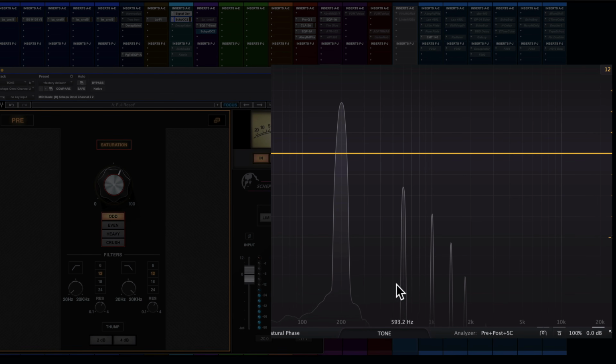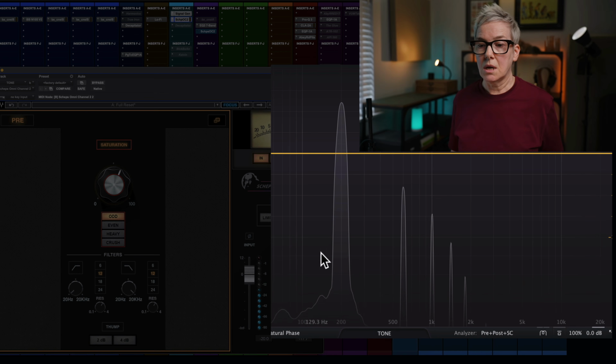So the original tone or note is 200 Hz, and odd harmonics represent the third, fifth and seventh harmonics and continue. We see that for 200 Hz we are getting a 600 Hz tone because 200 times third order, so 2 times 3 is 6, and then fifth, 2 times 5 is 10, so 1 kilohertz there, a harmonic, and then seventh on a 200 Hz tone, 2 times 7, 14. Okay, and on it goes. So those are the odd harmonics that are added to an original tone, in this case 200 Hz.